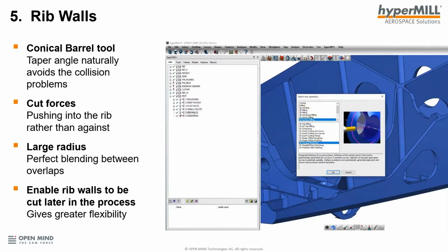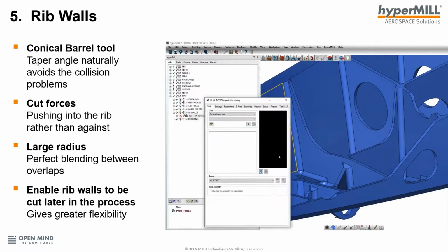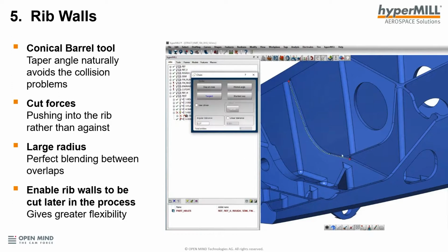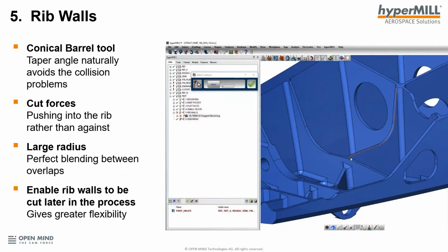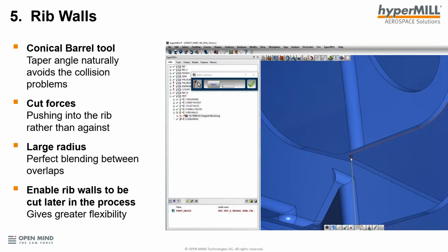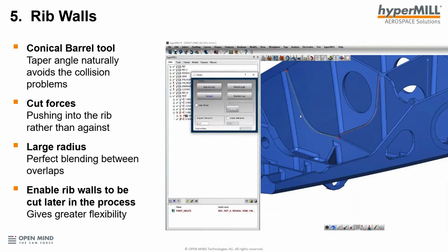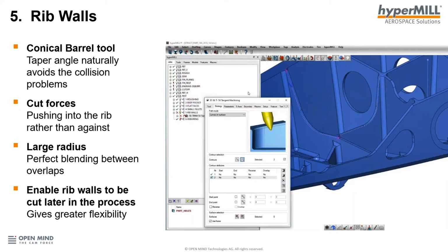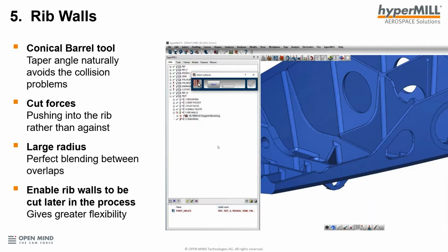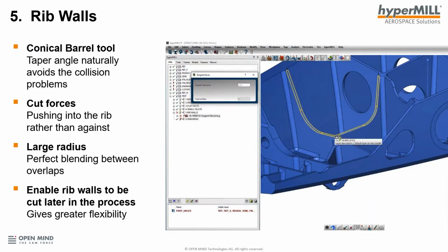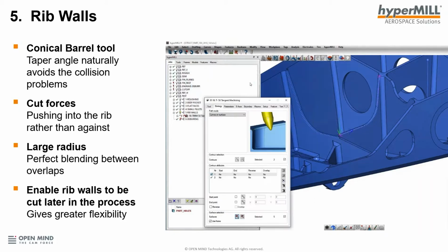How do we do this? Really simple. Pick the cycle, pick a tool. Now we're going to pick some radiuses. So we're going to interact and use a chain command, which is really nice. We've just chained tangentially these edges, and I don't want this one here, so I'm just deselecting it. So we've got it loaded. I'm then going to load another curve in at the same time. Good, we've got two. Now I'm going to tangentially select the surfaces that I want to run against.